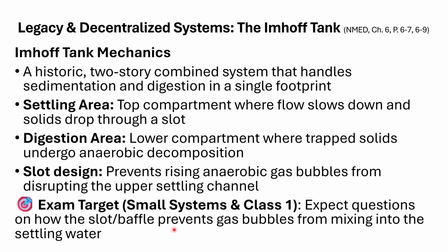Okay. For small systems, and none of you in here are going to go for your small systems cert, which is fine, particularly small systems, you'll get some questions on this. Class 1, you might get some questions on this, just one or two, not a whole lot. They'll ask how that slot or baffle prevents gas bubbles from mixing into the settling water. All you got to do is basically say it blocks the gas from migrating to the upper chamber. It's a seal. That's all it is. The design is a seal, just like the boot seal on the combined unit.